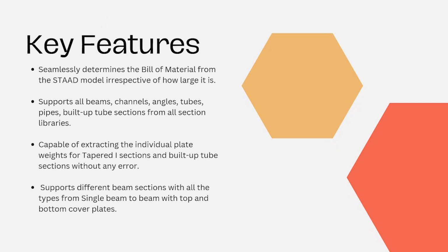Moving to the key features, firstly, this program seamlessly determines the bill of material from the STAAD model irrespective of how large it is. Say your model is around 5000 or 10,000 members. It will take the takeoff within 5 to 10 seconds.